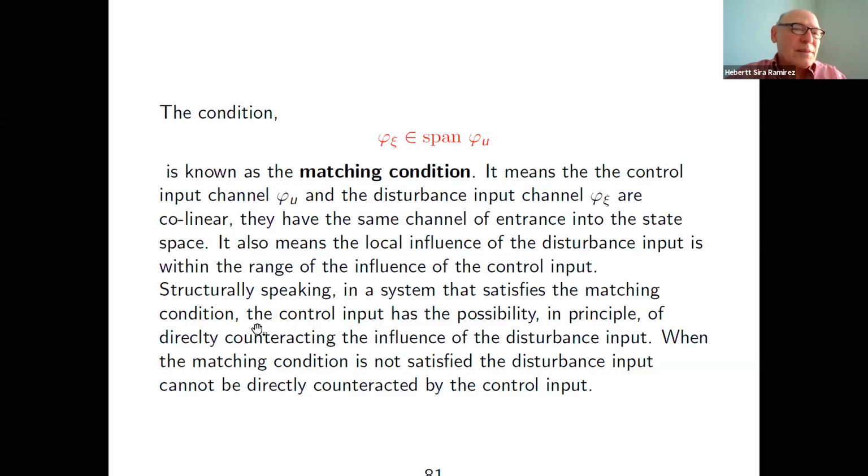Yeah, I think that's perfectly right, because in sliding mode control, the output that you're caring about is the sliding surface coordinate function. So the expression of your sliding coordinate in terms of the states. And that's one dimensional, let's say in the case of single input, single output.